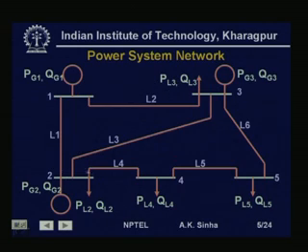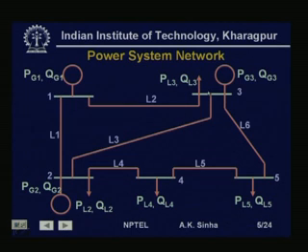In fact, most of the generating bus bars will also have some load connected, because if you are running a thermal power station, then the auxiliaries as well as the substation supplying local power for the residences in that power station all have to be supplied, and these are the loads connected to that bus bar. So, in general we have generating bus bars and load bus bars, and these are connected by means of transmission